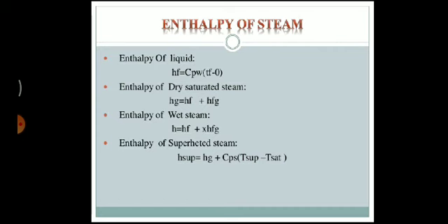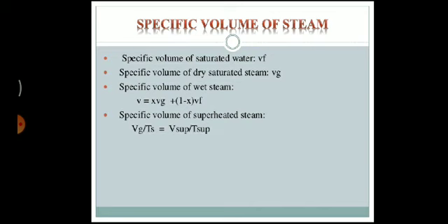Enthalpy for dry saturated state, Hg, that is Hf plus Hfg. Enthalpy of wet steam, that is H is equal to Hf plus x Hfg. Enthalpy of superheated steam, that is H superheated is equal to Hg plus Cps times T superheated minus T saturated.